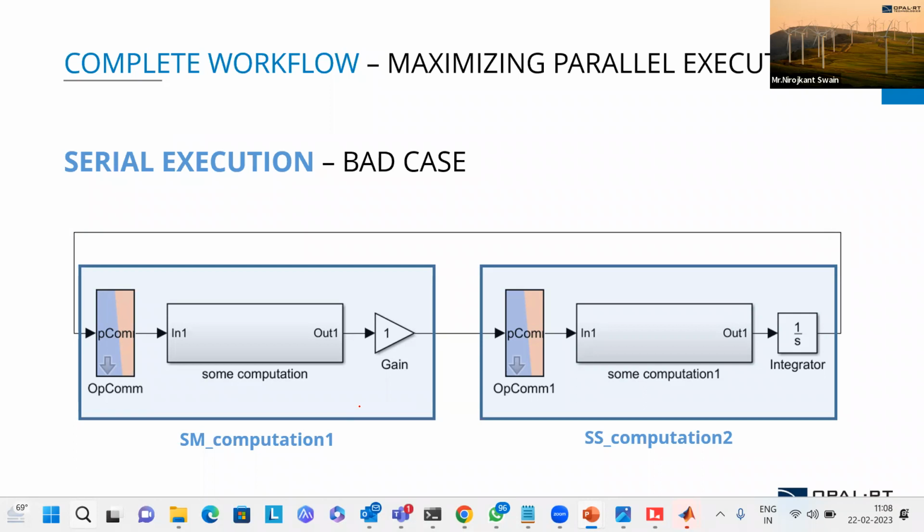Sir, is OPAL-RT limited to only simple control strategies, or can it also be applied to more complex ones? Can you explain what you mean by simple and complex? By simple I mean PI control, and by complex I mean reinforcement learning control. Yes, you can use it for complex control systems. My reinforcement control strategy works on an agent available in the MATLAB workspace, but in SM we can only include data which is available in the Simulink model.